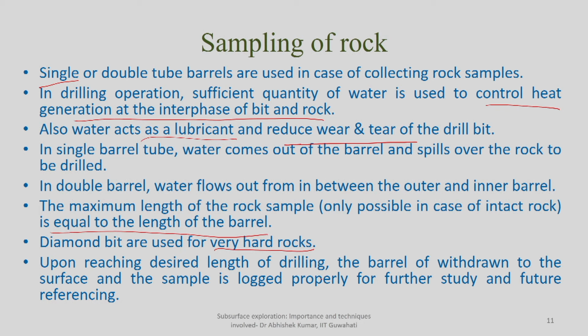Upon reaching the desired depth of drilling, the barrel will be withdrawn onto the surface and the sample is logged properly. As I told about soil also, at different depths you will have different rocks, soils. It's not like whatever rock you encounter at 5 meter, till 30 meter you will find the same kind of rock. It may not be mandatory that for the entire 15 meter you will find the same kind of rock. So you have to collect the sample, and it may be possible, because of fissures, cracks, or some disturbance caused by mechanical drilling operation, that the rock core sample may break in between.